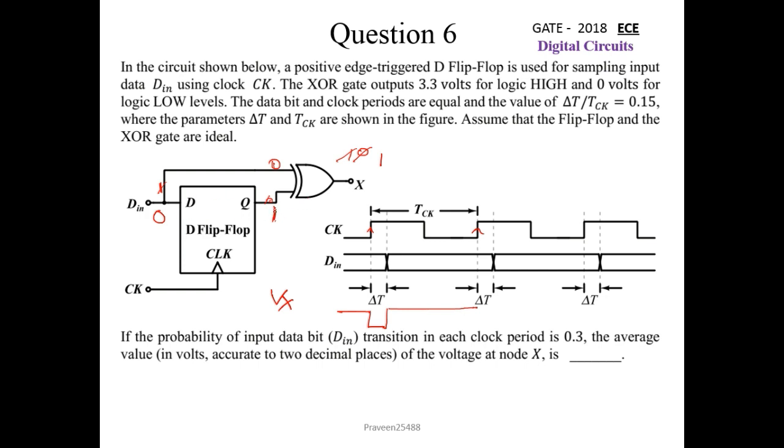As we apply the next clock pulse, the input at the D flip-flop will be at the output. So here from 1 it will change to 0, and here we see the XOR inputs are the same, so the output would be 0 here. So from 1 it would be changed to 0 again. So here it would be 0, and as the input changes from 0 to 1, here we see it is 1, and 1 0. The XOR output for input 1 0 would be 1 again. So here at the output we will get 1, and so on it carries out.